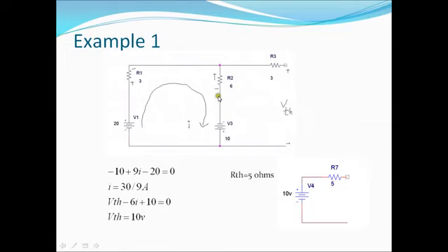So now let's see about the resistance part. In order to find R Thevenin of the circuit, if we have voltage sources in the circuit, we need to short them. If we have a current source, we need to open it. Since in the circuit we have just two voltage sources, make them short circuits. This is short, this is short. Then we get 6 ohm in parallel with 3 ohm. This is 6 into 3 upon 6 plus 3, which is 2 ohms. This 2 ohms is in series with this 3 ohms. So R Thevenin is 5 ohms.